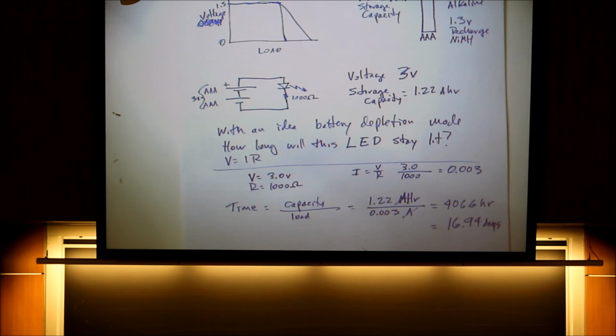Maybe to set your expectations of electronics projects that you're going to be doing in the future, right? The fact that we're drawing only 3 milliamps on a circuit is actually really good for very small circuits, small devices. But if you get anything like wireless, anything using any technology like that, it's probably going to draw a lot more.